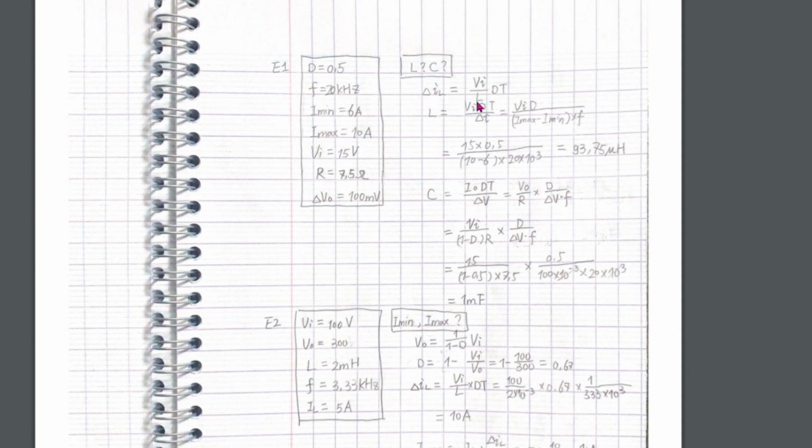We use the voltage ripple formula. Then we get the inductor. For the capacitor, we also have the formula. We only need to get the output average current by using the output voltage divided by resistance. We can use D to retrieve the output voltage from the input voltage.